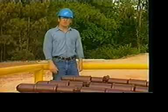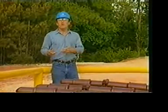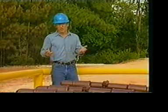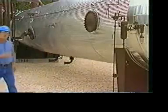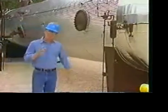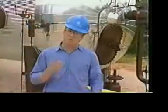Now, the amount of water in an emulsion may vary from a small fraction of 1% to almost 100%. Generally, older wells produce more water. No two emulsions are alike, and they must be tested frequently because over the life of a well, emulsions change and treatment processes must be changed accordingly.